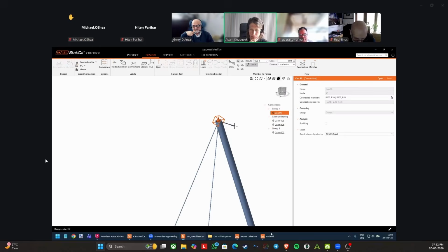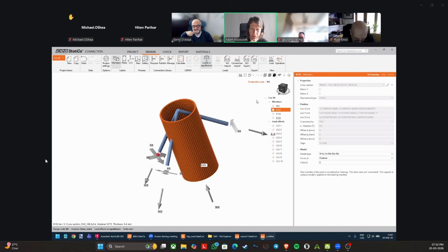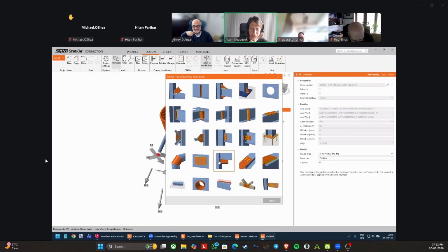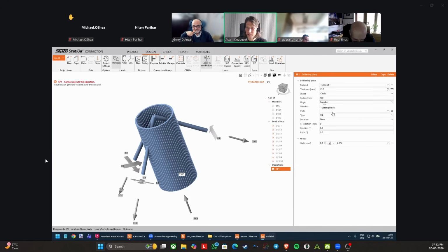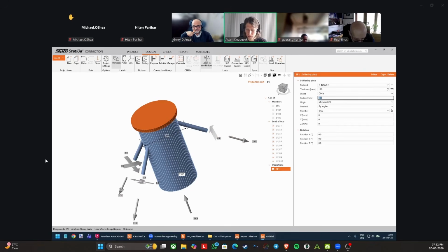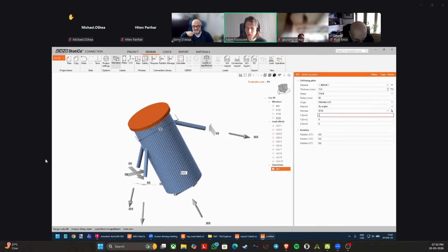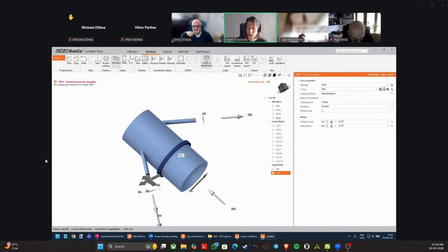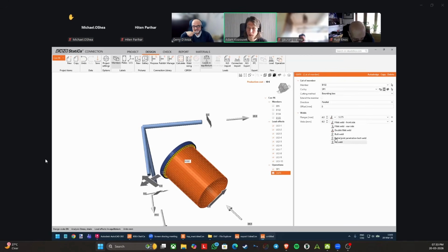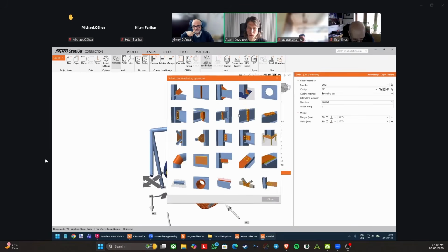What just happened is that I forgot to save my previous work, so I will quickly do that again. I turn off the weld here. A little repetition: radius 95, and this was minus 220. Then I add the cut by plate. Okay. Now the stiffening member.